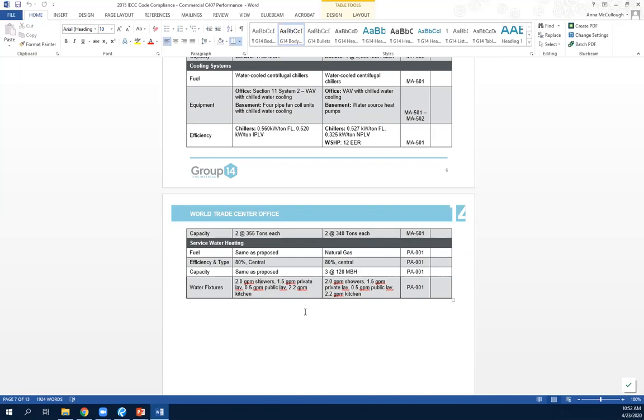Absolutely. Yeah. And then a couple more. Now this one's going to be all over the board, but I'd be curious to get your thoughts. What are the differences in design cost, if any, between performance versus prescriptive paths? That's a great question. So normally what we see is a building wants to go through the performance method because they want to increase their glazing. So right away, right off the bat, that building costs more than a prescriptive building. Glass is just so expensive.